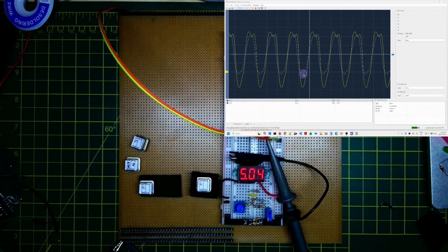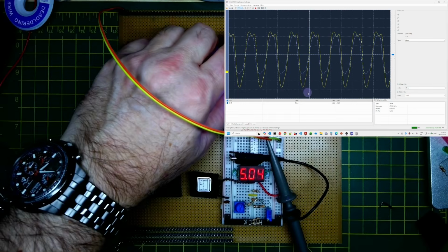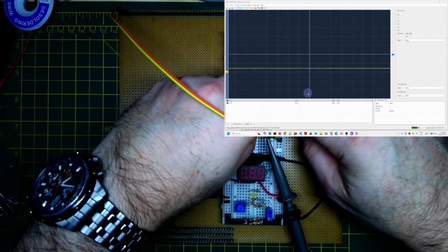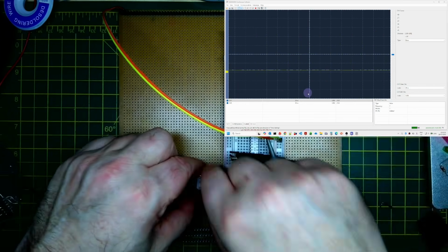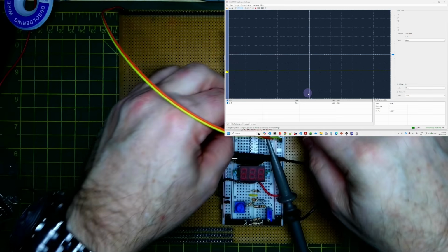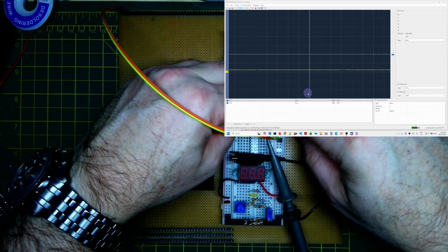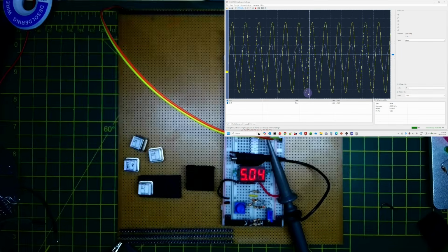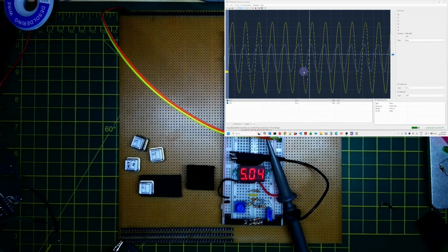Then finally, as a bit of a test, let's see what happens with 40 MHz. Now I wouldn't expect 40 MHz to work very well, but we'll just see whether 40 MHz will actually work over through these chips and on the bus rails. Okay, so it is, but however, the undershoot now over the bus rails is almost 2.3 volts, I would say. Now that certainly is not good news for logic chips. You probably wouldn't want to feed that in. It's only for a few nanoseconds that it's occurring, but even so, it's probably not great.